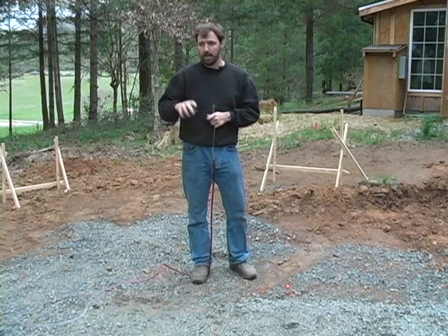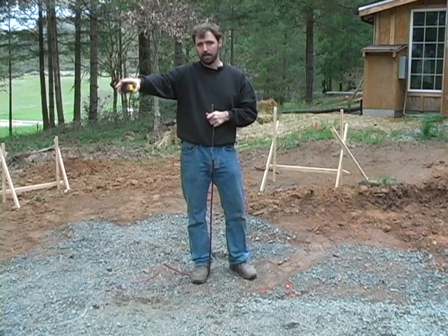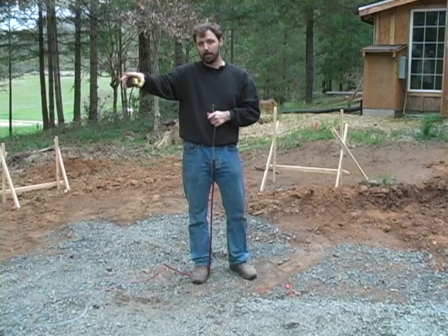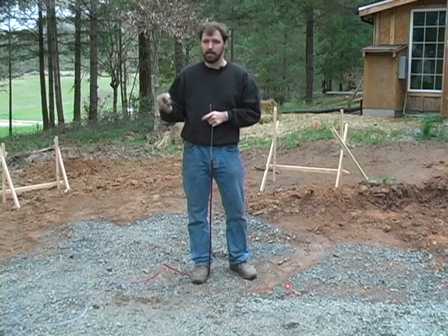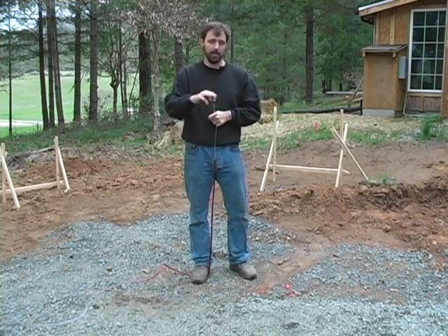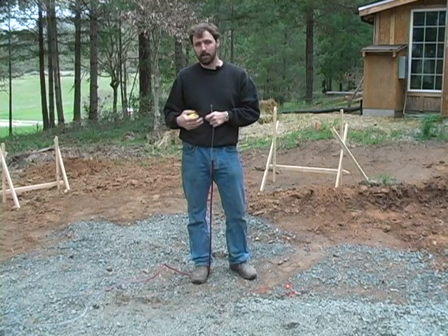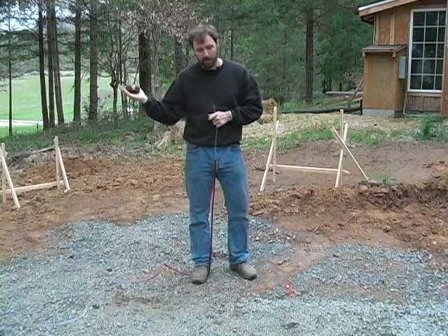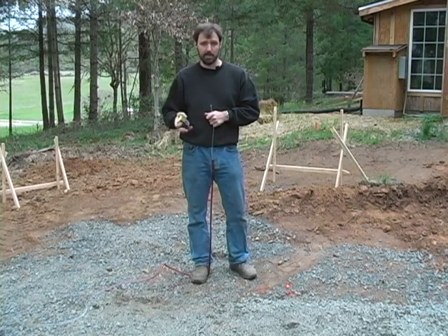That's the case here. Now as we go this direction, we had a different finding. We found that that end was a little bit higher, so that had a smaller number. We had 33.5 over there instead of 34. So we know that we've got some higher corners and some lower corners. Well, now that we've established the high corner, we can go from there and pull out the rest of our form boards. For a small structure like this, it's easy to do it just like that and then level them as they go.